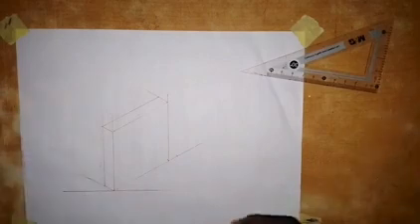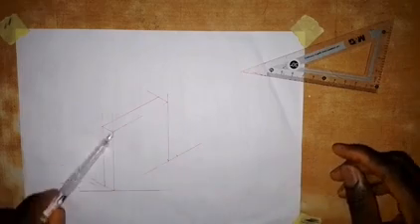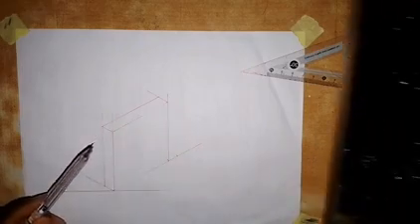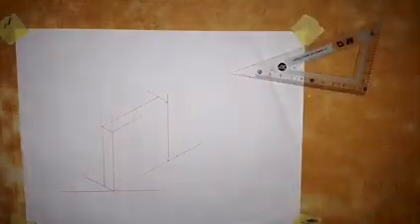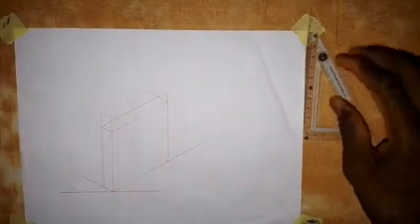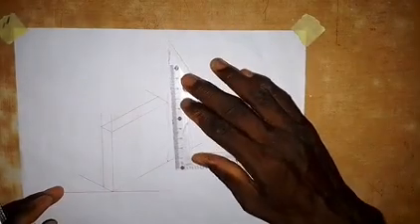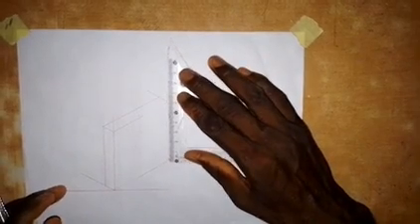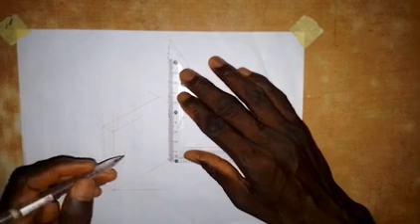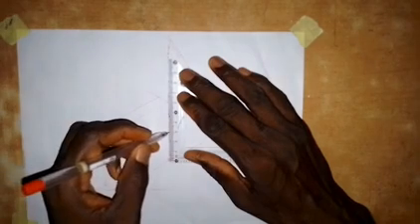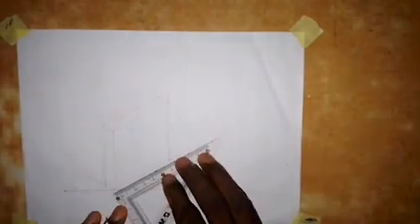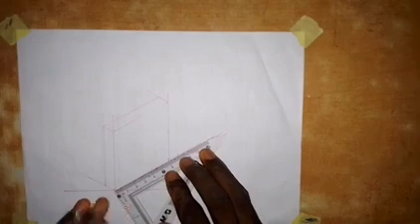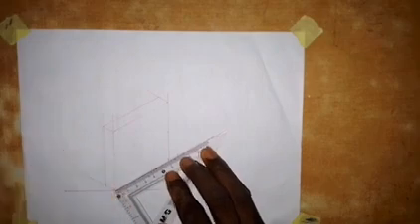And then the next thing that we are going to do is construct this semicircle that we have here in the elevation. So we are going to construct it, and this is how we are going to do it. What we are going to do first is to divide this 60 millimeters square into 2 equal parts. So we have this is 30, and then we also divide into 2 equal parts down here. So we take 30, so this is the midpoint.